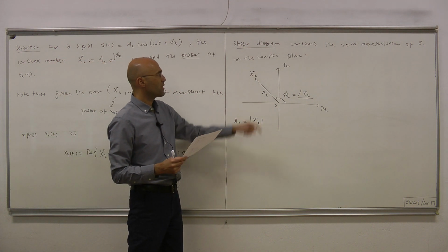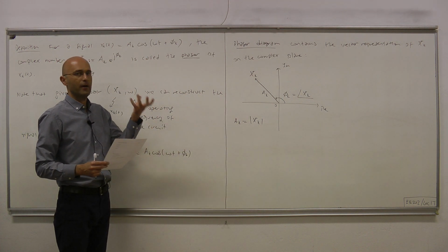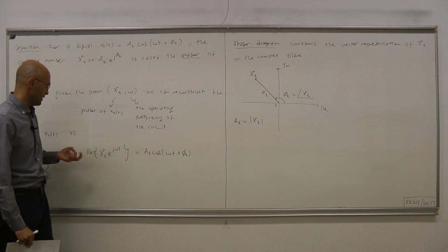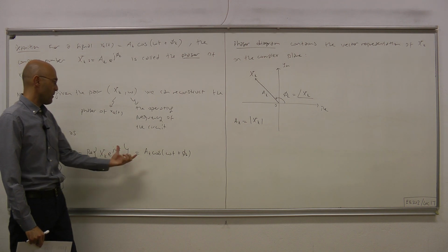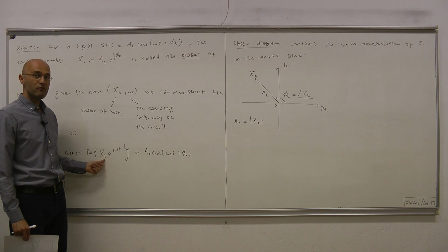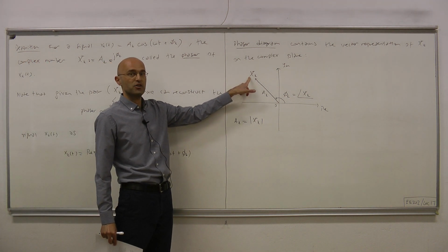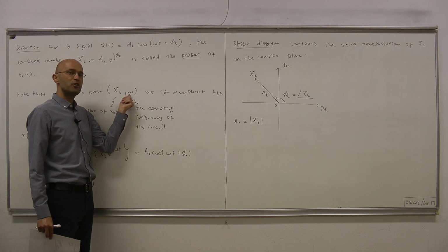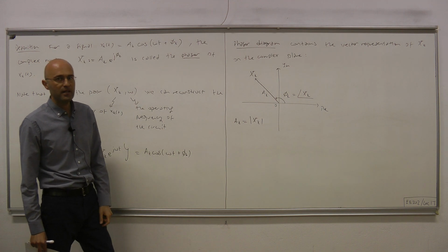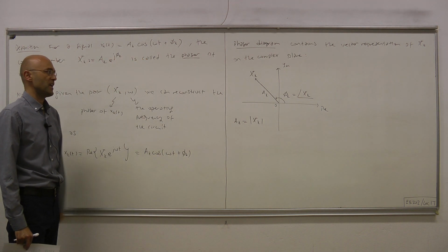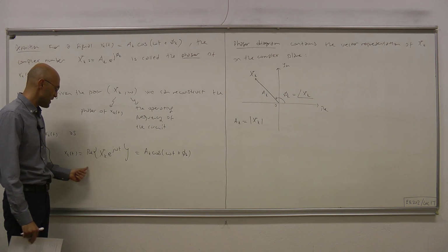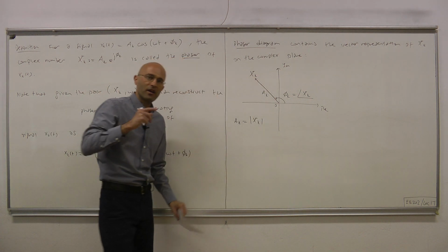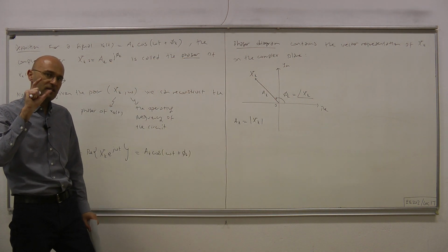Once we have this diagram, it's easier to interpret or talk about this relation. We have the phasor, this vector xk, and given the information about the frequency of oscillations, we will now generate the signal, lowercase xk, the time domain function. Here it says to take that xk and multiply with e to the j omega t. If you multiply any vector with e to the j omega t, note that the magnitude of e to the j omega t is always 1.